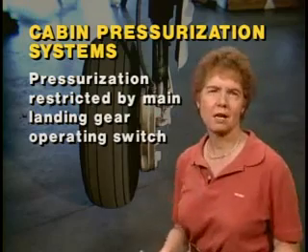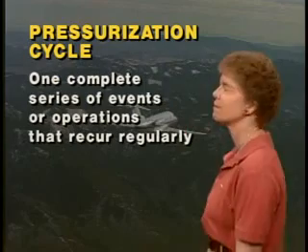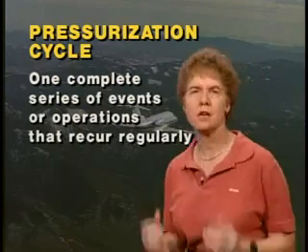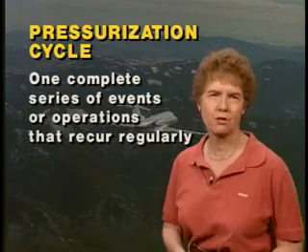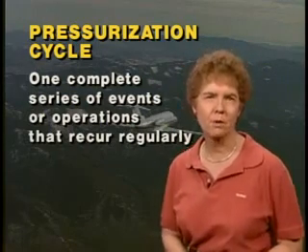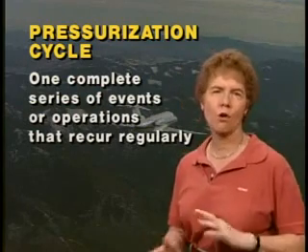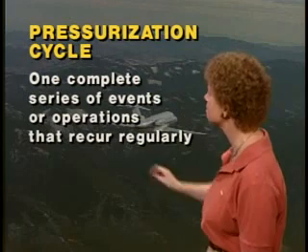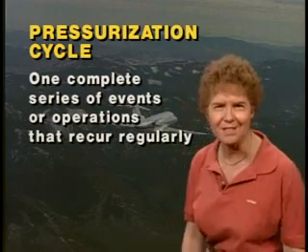Now, what exactly constitutes a pressurization cycle in an aircraft? Well, a pressurization cycle is considered to be one complete series of events or operations that occur regularly in the pressurization system. It is not one takeoff and landing, because it could be a very short, low-altitude flight where you don't pressurize at all. And it is not reaching maximum pressure differential in the aircraft, because if it's a low-altitude flight, you might not get all the way to max pressure differential. It's one complete series of events or operations that recur regularly in the pressurization system that constitutes that pressurization cycle.